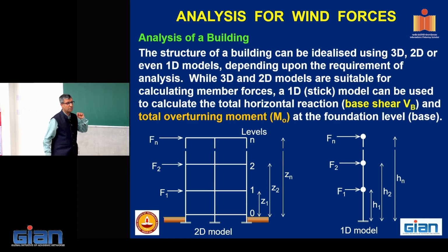The idea about the stick model is to see what is going to happen due to the vertical distribution. So these are lateral forces acting at different heights. The summation of these forces creates what is called the base shear. The base shear is the important quantity of any lateral force. Next, when we come to the earthquake, it will be even more important.